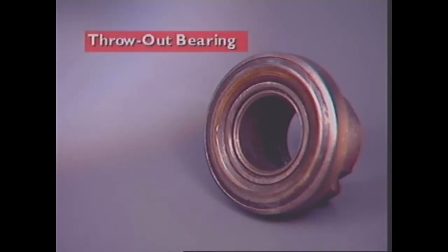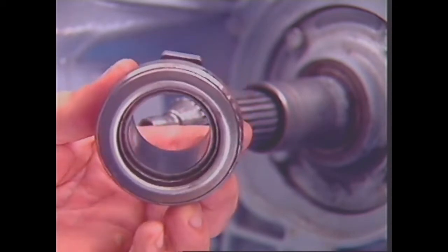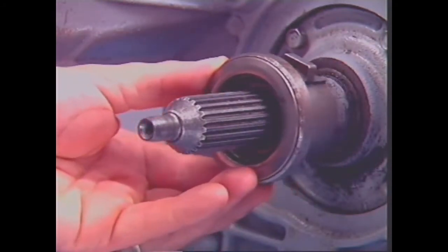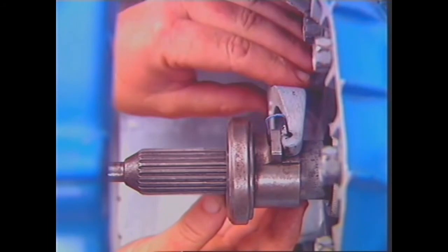This section examines the throwout or release bearing. The clutch release bearing can be a thrust-type angular contact ball bearing supported on a carrier. It slides on a hub or sleeve extending from the front of the transmission. The bearing carrier locates on the clutch release fork.